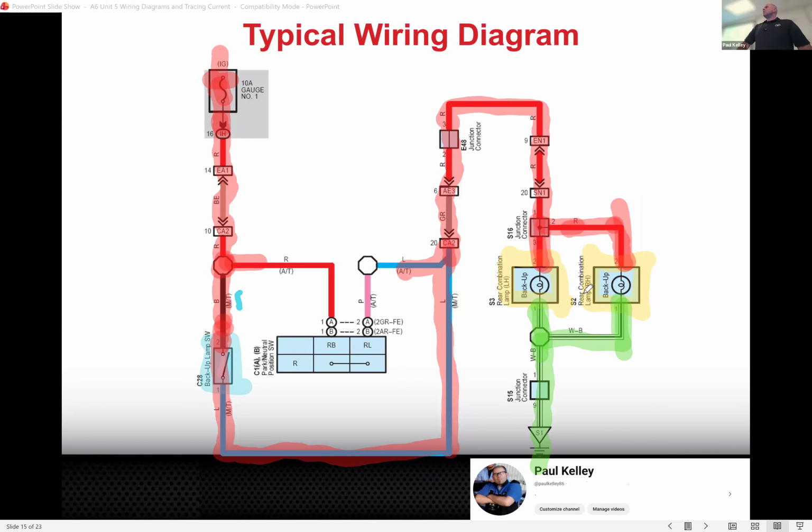And then if we've correctly traced that, this is where I'm going to try to show you the value in tracing it. Although, to be honest, once you have a lot of experience, sometimes we don't always trace it. You can just visually see and be like, oh yeah, I know where it should have 12 volts. But when you're new, you really want to trace it, especially so you don't get yourself confused. Let's just say, you understand the colors, right? So everywhere that's red should have about 12 volts-ish.